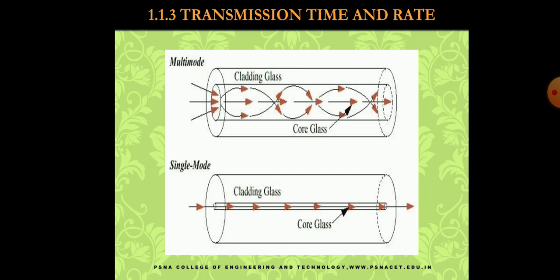And the second region of coverage of this topic is the bandwidth. Multi-mode fiber bandwidth is limited by its light modes, and the maximum bandwidth at present is 28,000 megahertz per kilometer for OM5 fiber, while single mode fiber bandwidth is theoretically unlimited because it allows only one light mode to pass through at a time.